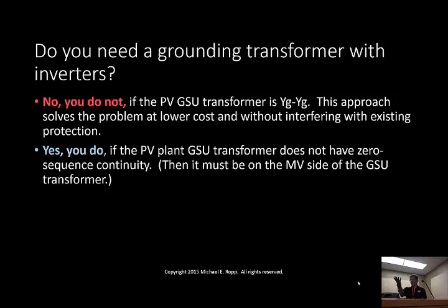There's an issue, we were just talking about this a minute ago as well during the break, that some photovoltaic inverters today don't want to face a grounded Y winding on a transformer. And it has to do with the way they detect arc faults on the DC, or ground faults on the DC side. If we have 2 grounds, an AC ground and a DC ground, their ground fault protection is going to be tripping off all the time. So they want an ungrounded AC connection. And really, that's where a lot of the problem comes from. So time to start working on figuring out how to solve that problem.